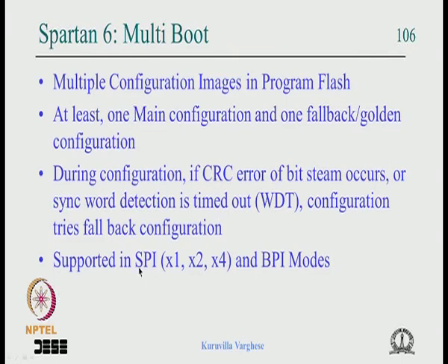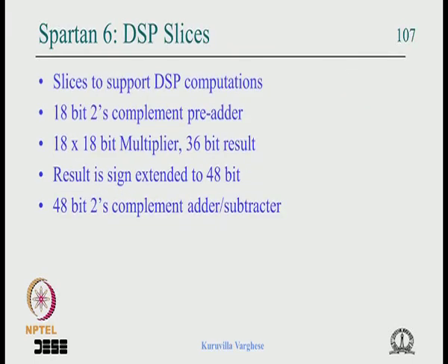And this scheme of multi-boot is available only in the SPI based flash PROM and the BPI based flash PROM. So in both it is available. It's a very good option if you are deploying FPGAs in the field, you should think of multi-boot, encryption and compression and all that, which will improve the reliability and improve the security, all that part.